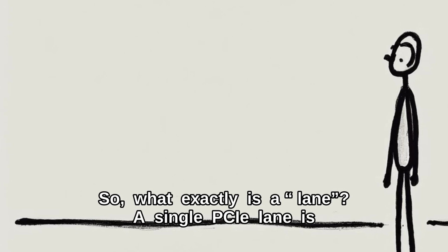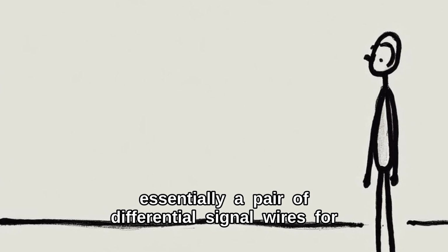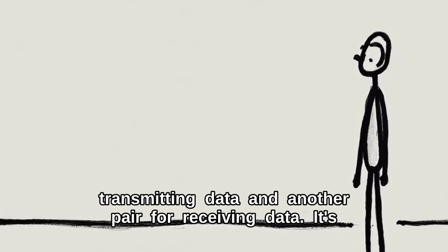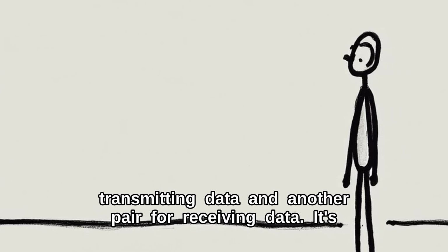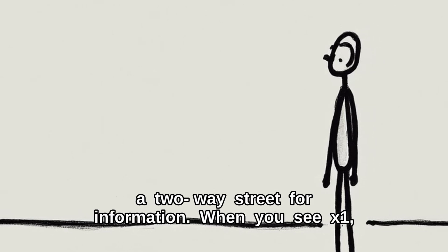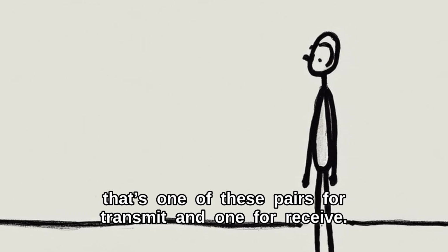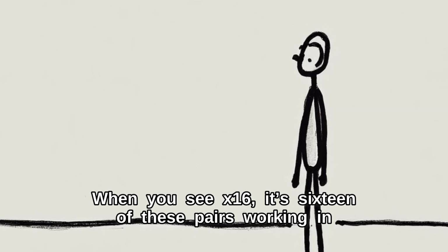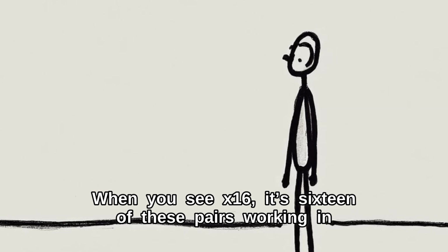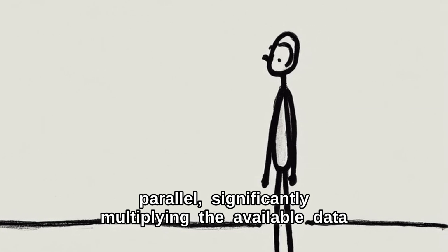So, what exactly is a lane? A single PCIe lane is essentially a pair of differential signal wires for transmitting data and another pair for receiving data. It is a two-way street for information. When you see X1, that is one of these pairs for transmit and one for receive. When you see X16, it is 16 of these pairs working in parallel, significantly multiplying the available data bandwidth.